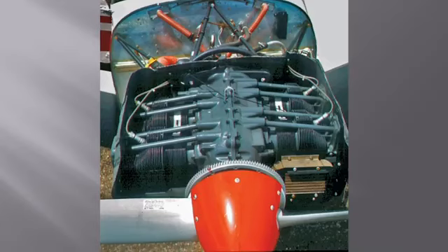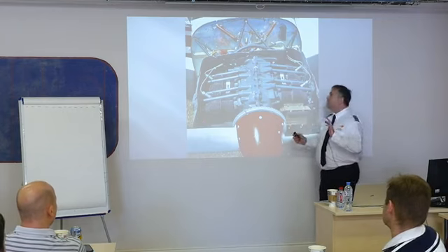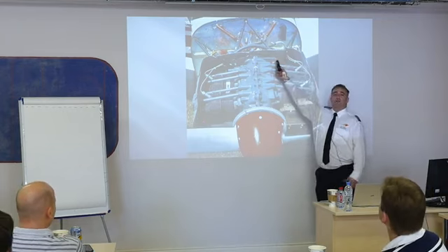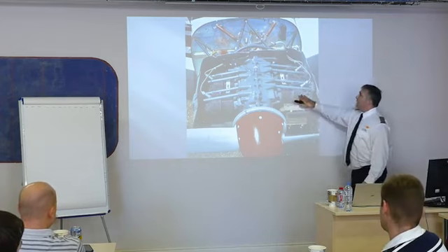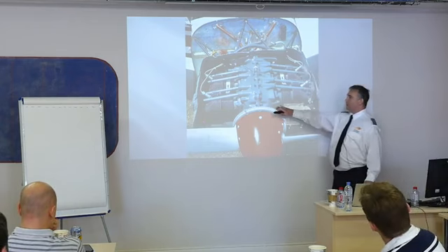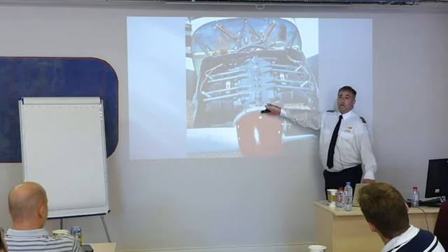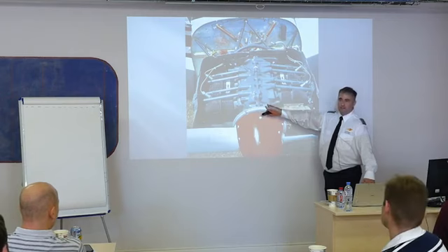Okay, power plant. This is our machine. This is a different type of airplane. You can see the firewall in the back, which just means if there's any kind of fire produced by this engine, any combustion that occurs on the outside, that fire will separate from me. It's separated from me with this firewall, okay? And then you've got the motor mounts that bring it over here to the different cylinders and to the engine crankcase. Now, we start talking pistons, crankshaft, crankcase, connecting rods.